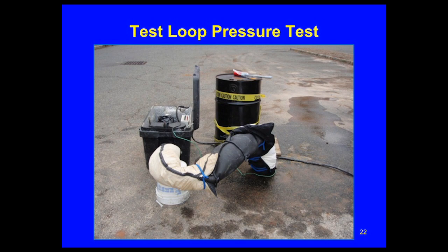And we watch and measure the temperature of the water in the pipe change over time. And that change in temperature is a function of the Earth's thermal conductivity. Once that thermal conductivity is understood for this specific location, then a mechanical engineer could model that and then design the system specific to this site.